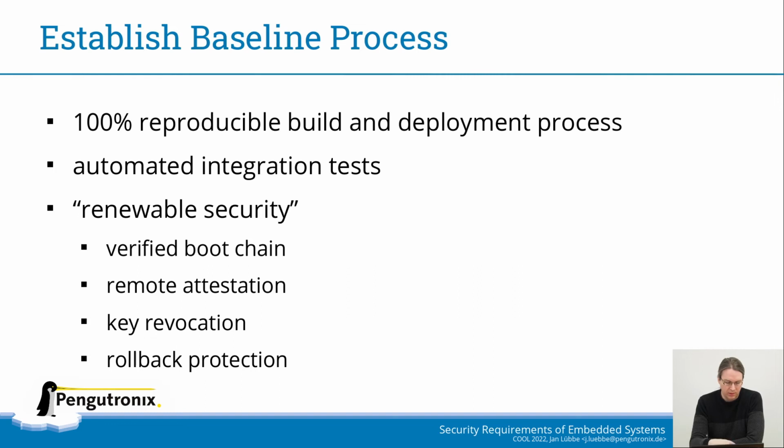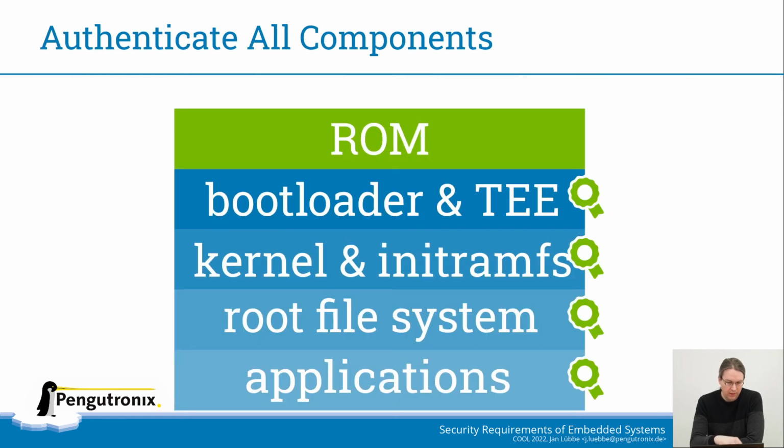So this is a good argument to add something like verified boot or boot authentication to systems which would otherwise not really need them because they're not in an exposed environment so much. Basically your authentication chain starts with the ROM in the system on a chip that is fixed and known good. That in turn authenticates the bootloader, and each step in turn authenticates the next one.